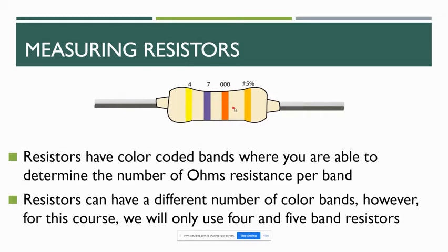So that's why they use these colored bands. You'll have to find what's called the tolerance band. It's hard to see in this diagram, but it's usually a little further away. The other three bands are usually closer together. And this is usually a shiny color. Usually, for most of what we're going to use, they should be gold in color. You may occasionally come across one that's silver. Okay, that's the tolerance, or how accurate the resistor is to the actual measurement.